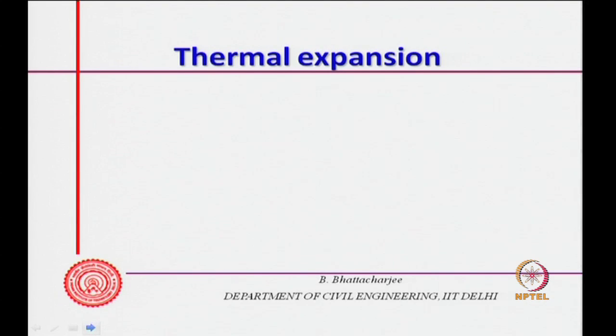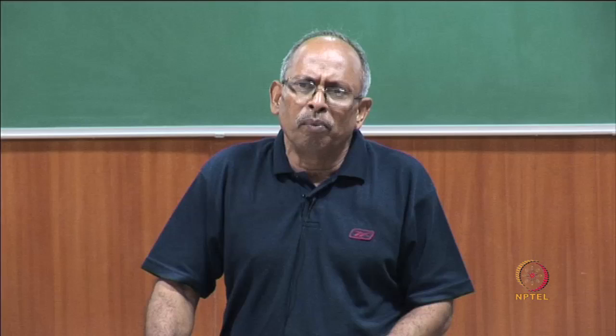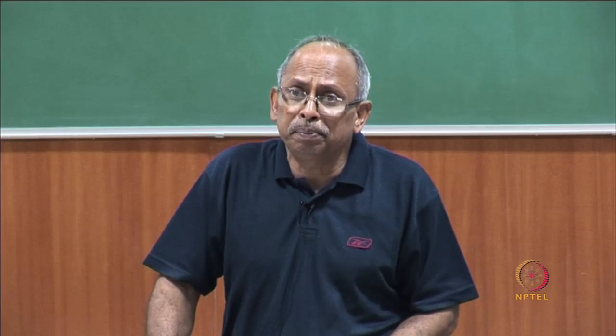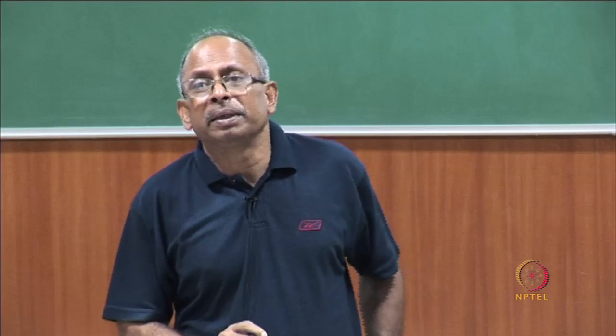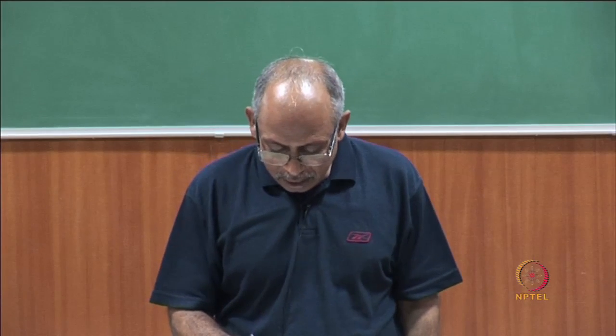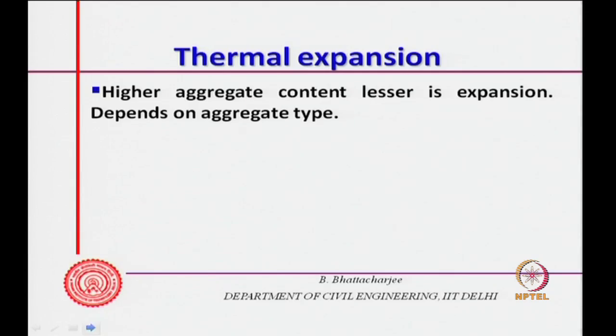Now, next we can look into thermal expansion, which is almost a related matter to shrinkage and expansion, right, because this is also a kind of dimensional change. And you see, the coefficient of thermal expansion is important, because, for example, if I am using a reinforcement, let us say steel, of course, we do use, its coefficient of thermal expansion should be similar to the concrete.